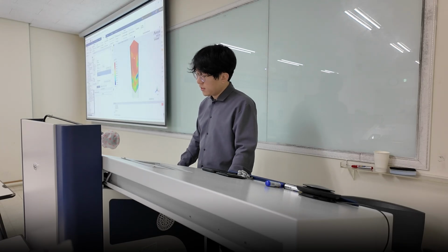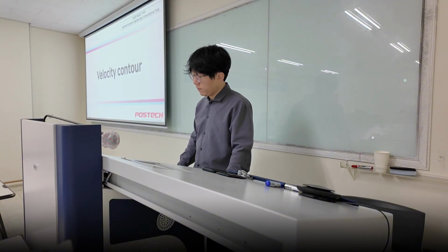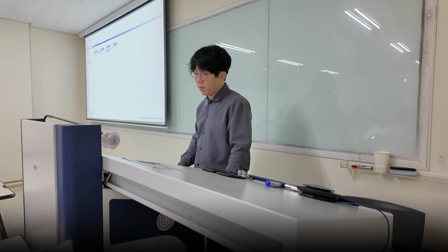Once the results are prepared, you can draw contours of pressure and see velocity at the same time, and you can save and quit these. So this is what you're going to have. If you want to run another project, you can copy and paste these nodes, and then you'll have them easily modifiable within new simulations. Also, if you want to keep these steps and just change the results, you can drag and drop a result node here, and then connect this solution to this node as well. So you're going to have two outputs from one solution node.